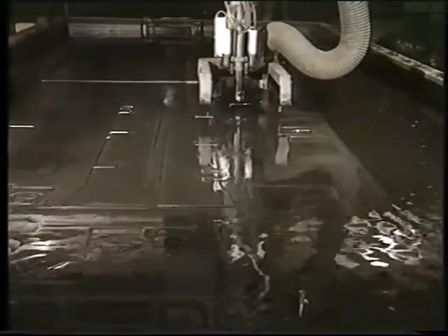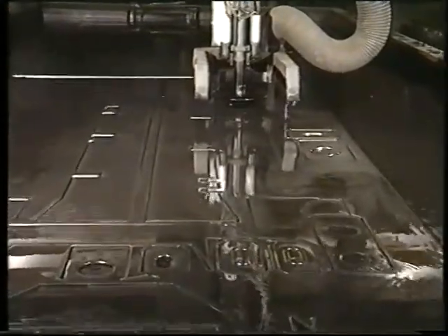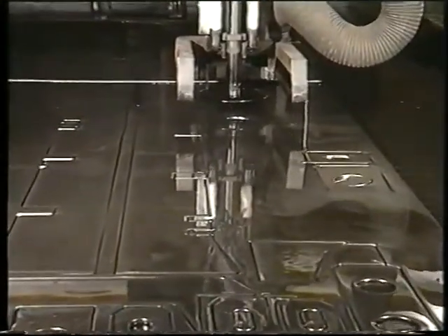This is what the cutting operation would look like out of the water. In the early 1980s, AGA Traction began exploring the possibility of robot welding certain parts of our bogey frames. At an early stage, it was clear that robotization would pay off, provided the tolerances of the plate blanks were good enough. Since our blanks lie within 7 and 15 millimeters in thickness, plasma cutting seemed the best alternative. Besides, with plasma it was possible to cut underwater.